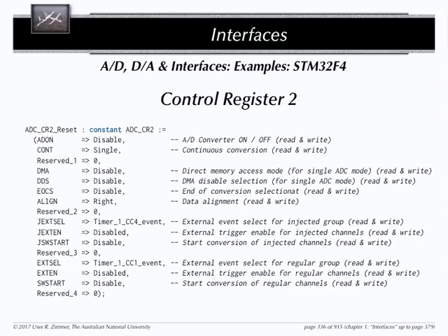Multiplexers. What's a multiplexer? It's for routing signals within the chip. Yeah, so it's more of an internal thing to connect different devices. You have a bunch of devices and a bunch of other devices, and you want to connect them in interesting ways. Often this is part of the interrupt management: which of these devices is supposed to be able to trigger what kind of interrupt, connect with what kind of device and trigger what kind of effect. Lots of possibilities to switch that in a clever way.